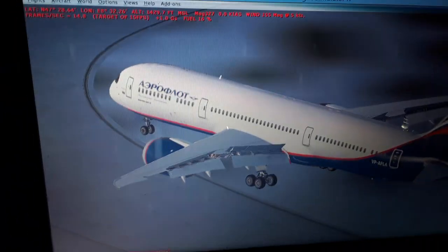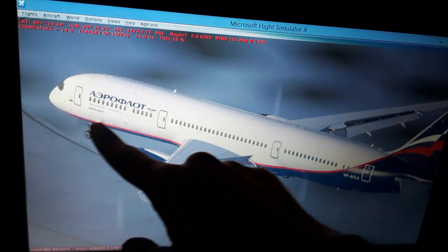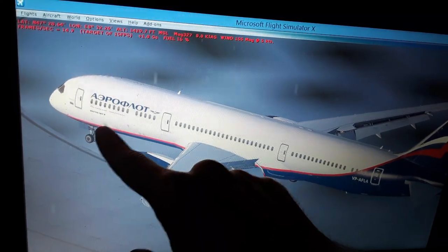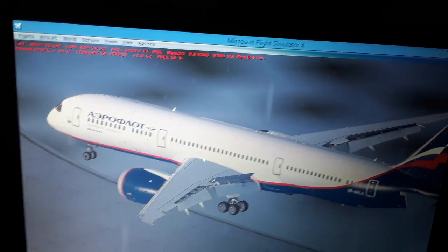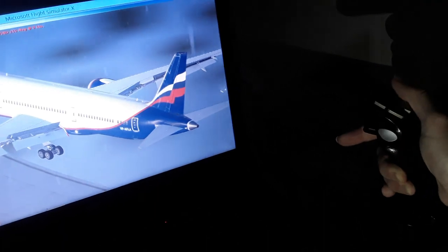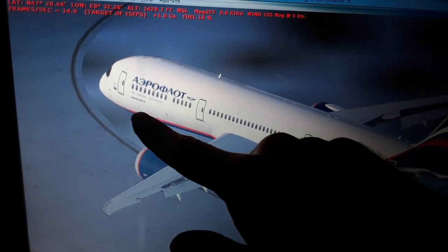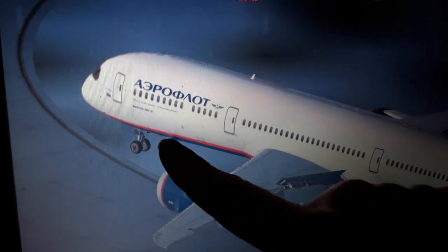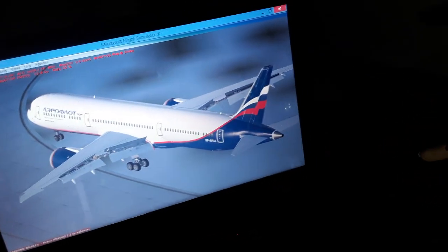For directional control, we can also use the nose wheel of the aircraft to make left and right turns, like 76 degrees, alongside the rudder, from 0 to like 45 knots or 70 kilometers an hour in takeoff. Then it decreases as we increase the airspeed. The rudder is aerodynamically effective at 45 knots, 70 kilometers an hour approximately, or 80. So the nose wheel will decrease from 76 degrees deflection left and right to like 7.6 from the computer automatically, as we increase the airspeed, as the rudder becomes aerodynamically effective.